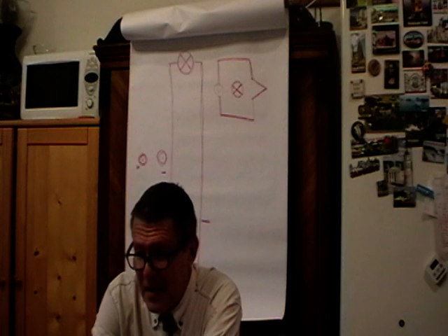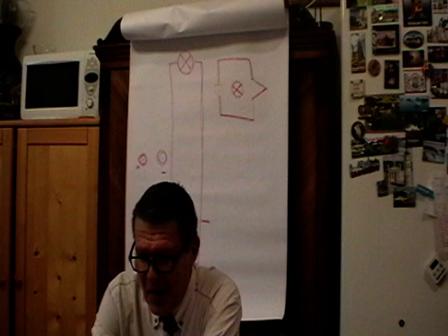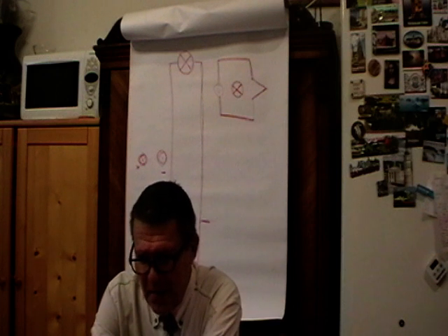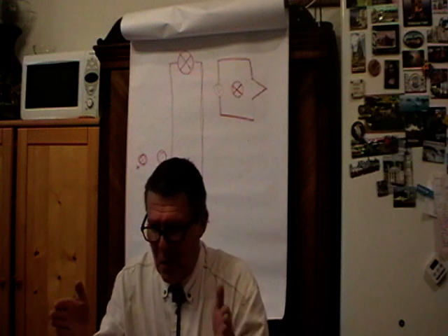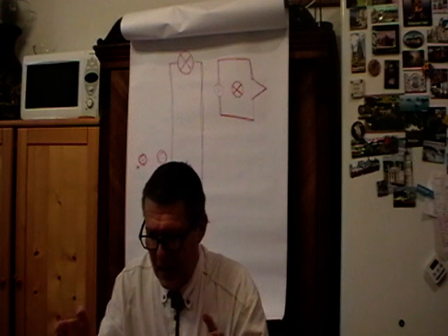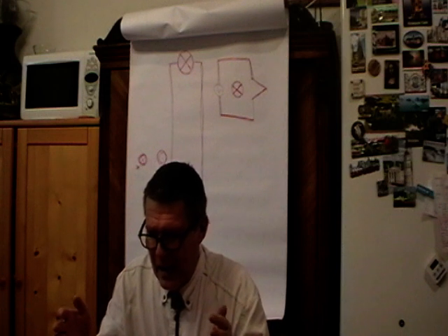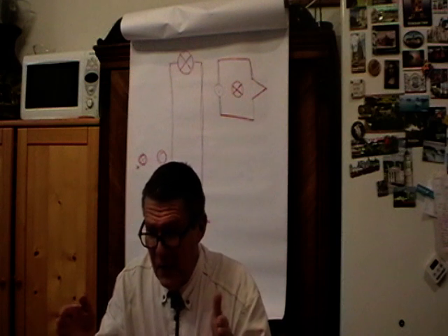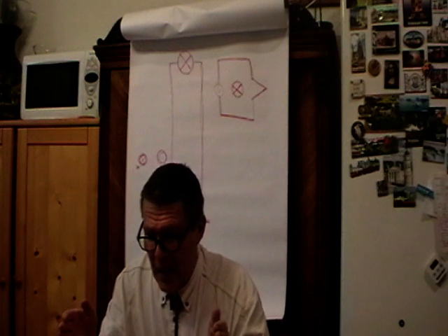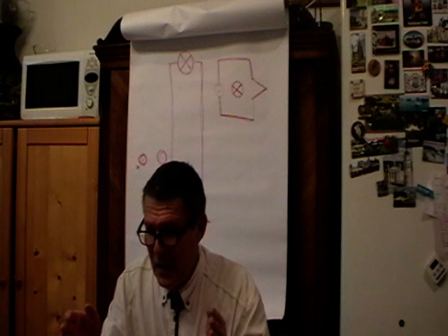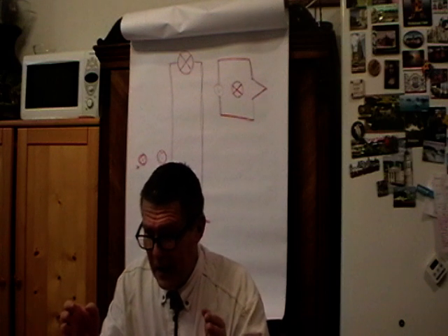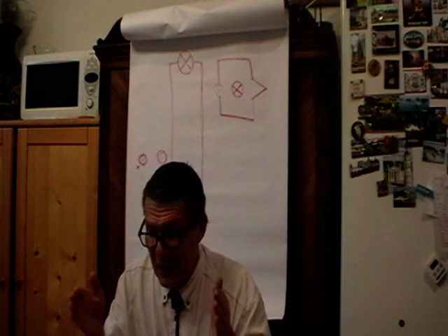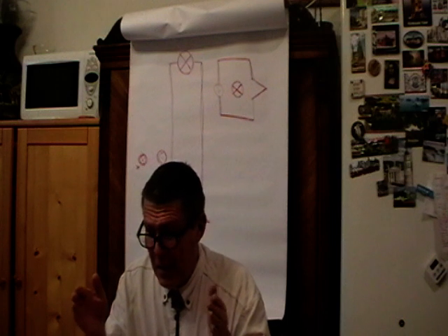And there is a third system in the tram, which by the tram drivers are called booths. There are special boxes you can see between the wheels, something that looks like a big metallic box, but in fact inside that is a strong electromagnet. This electromagnet is fed not from the outer network but from the accumulator of that tram, so it would work even if there is a blackout.